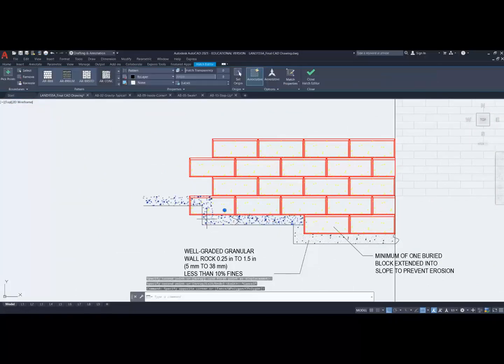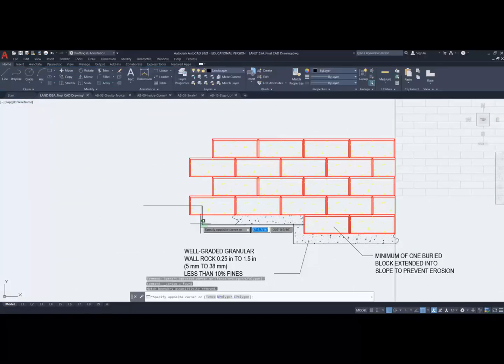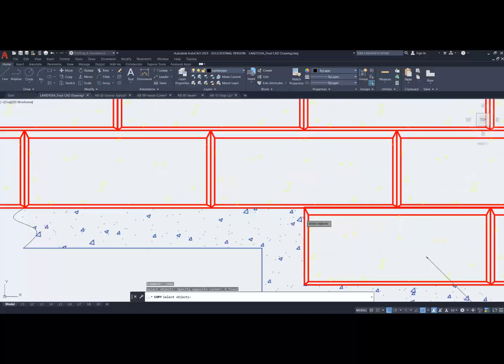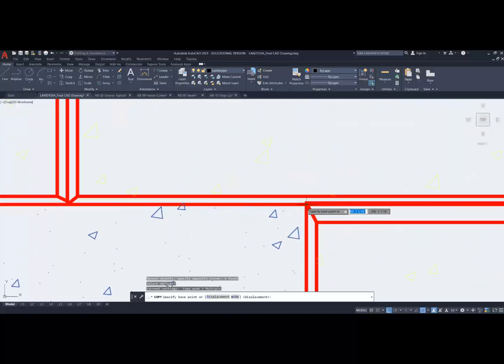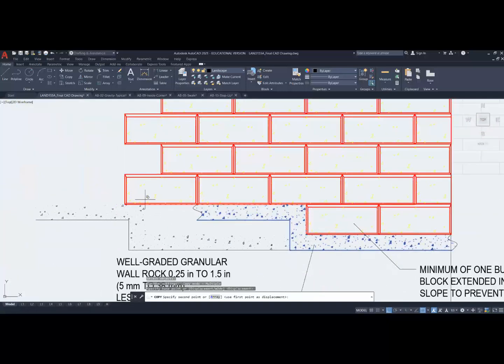Okay, now you can see I'm erasing and deleting. Why? Because I don't want to measure a lot of this stuff out. So in order to avoid measuring it, I'm just using it as a reference in another location. Now I'm going to copy this. There's my hatch. There's my line work. I'm not going to include these lines because I want to show where they're actually going to go. And now I'm going to use that reference of where it is. See the inaccuracy in their drawing here to where I want it to be, that corner there.